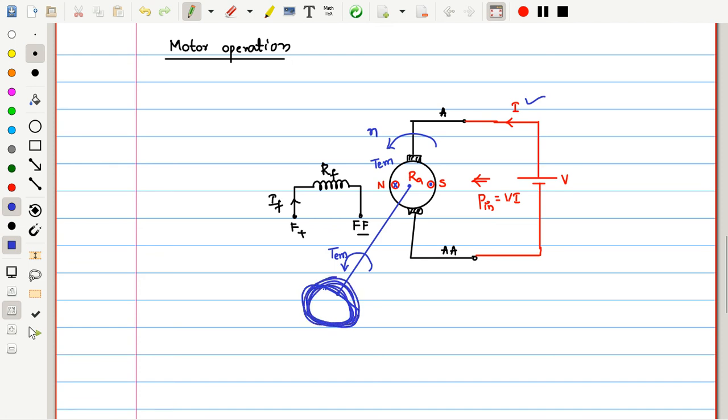But whenever I connect some load over here, some mechanical load, let us say some big sugarcane machine, where we need to rotate some gear mechanism by this shaft of the motor, once we switch on the machine, once we insert some sugarcanes inside this, then some load will be applied. As a result, there will be load torque generated which tries to act opposite to the electromagnetic torque. Just understand up to this extent how, inside the mechanism, this electromagnetic torque is opposite to the load torque.